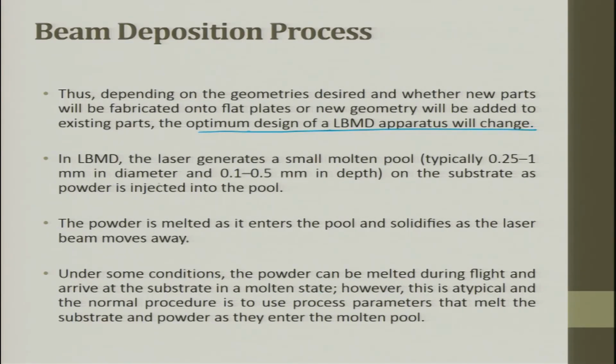In LBMD, the laser generates a small molten pool on the substrate as powder is injected into the pool. The powder is melted as it enters the pool. At the pool you will have a laser which is getting focused. What is the pool? The pool is a melt, and it solidifies as the laser beam moves away, instantaneously. Under such conditions, the powder can be melted during flight. That means to say, before dropping, during the flight itself, the powder can melt.